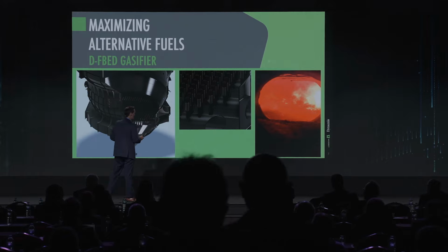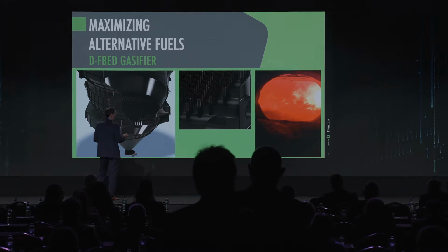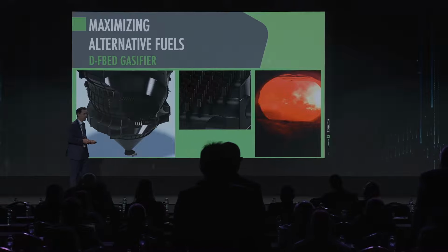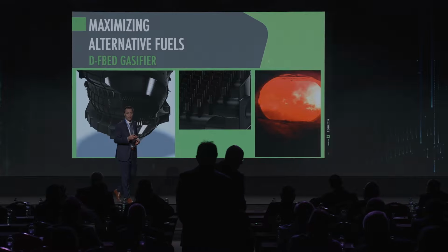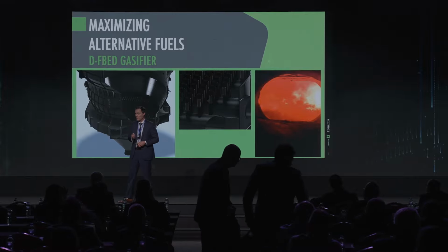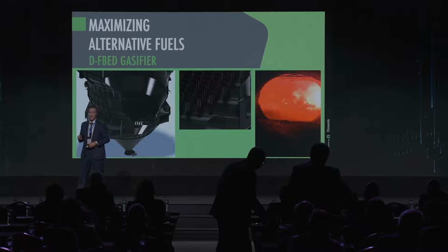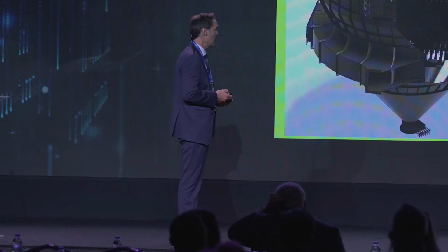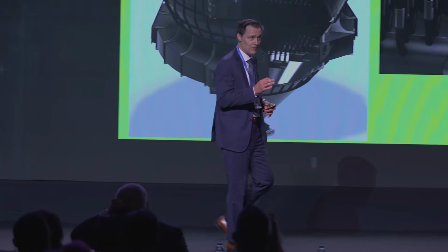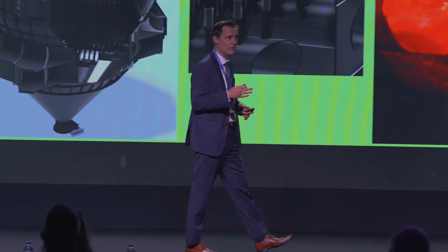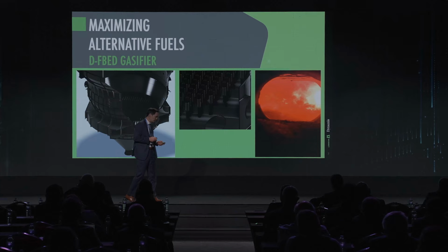So hot sand also acts as a thermal inertia that allows for fluctuations in the fuel moisture and the fuel particle size. If I would choose a single word to define the fluidized bed gasifier, it would be stability.